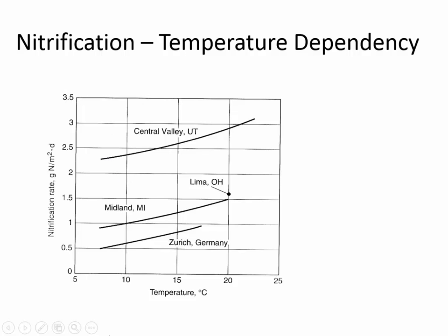But even at pretty low temperatures, you know, at 7.5 degrees Celsius, that would be pretty cold for water, the water temperature will increase and decrease through the seasons, but there is some lower limit to the temperature that you can expect to see at a treatment plant, just because the water is coming from people's homes. And so when you discharge water to the sewer, it's at least as warm as your house, and sometimes warmer if you've been taking a shower or washing dishes. So by the time it gets to the treatment plant, it's still relatively warm.